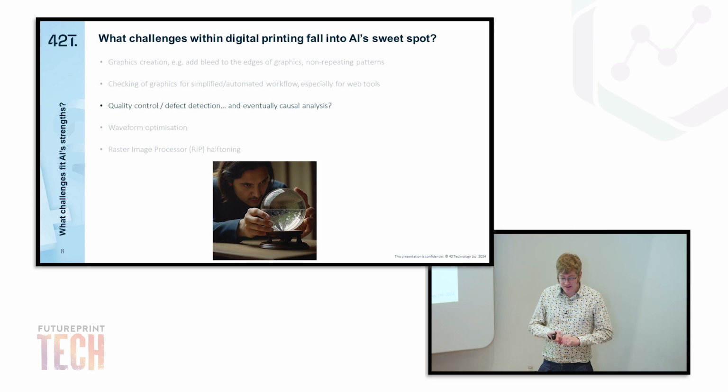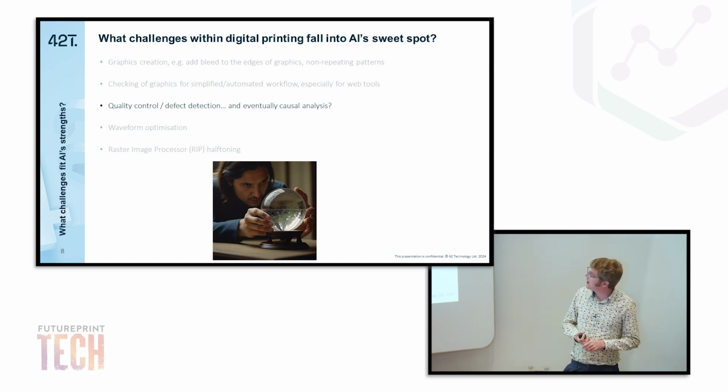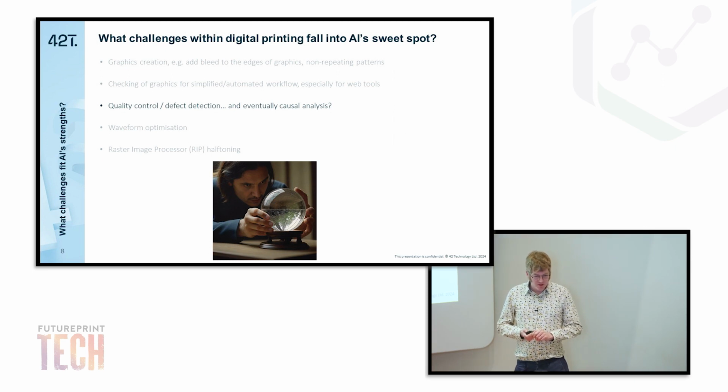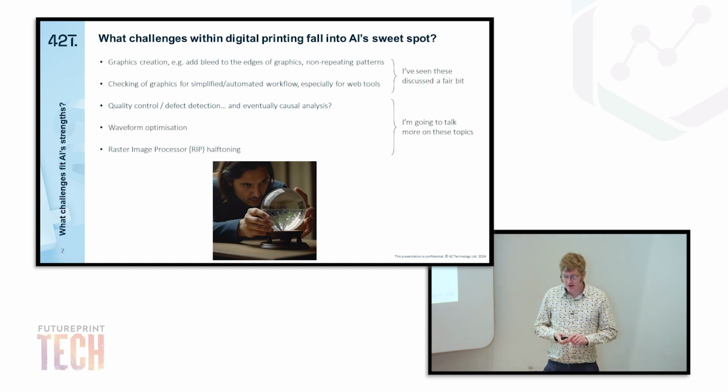Quality control and defect detection, and eventually causal analysis. Waveform optimization, so actually how we're driving the inkjet heads themselves. And also part of the RIP, the raster image processor, half-toning process. So yeah, those top two I've seen discussed a fair bit, and they've already come up today, so I'm not going to talk about those. We'll jump straight on to the bottom three.